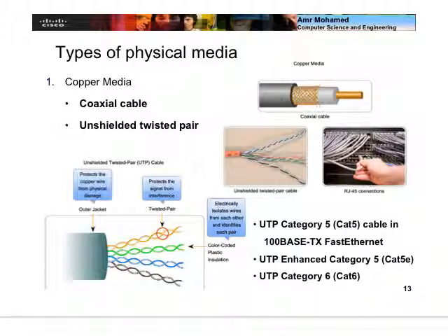However, remember for the twisted pair, each wire has a small bandwidth, but we have 8 of them. We can use 4 of them for one direction and another 4 for the other direction, right? So you have separation for full duplex communication. Even though each wire has a shorter range of frequency, we have 4 in parallel, so the 4 in parallel can in fact have a higher bitrate compared to coaxial.